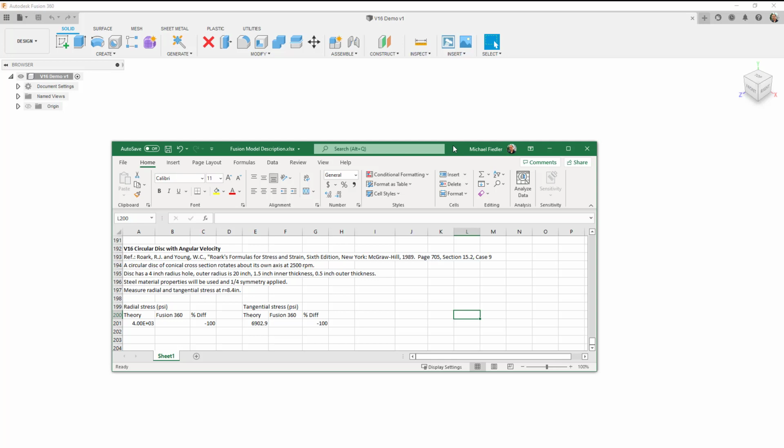This one, actually, I used not that long ago. A user reached out to me and they said, "Hey, we have some rotating equipment that we want to analyze. How should we approach this? Can we do a dynamic analysis? Can the software rotate this thing at that speed and let us see what the stresses and displacements are?" And the short answer is yes. Technically, you can, in some cases, take something, apply something like a prescribed rotation to it, bring it up to speed, and see what the outcome is. But it is a rather computationally expensive way to do an analysis.